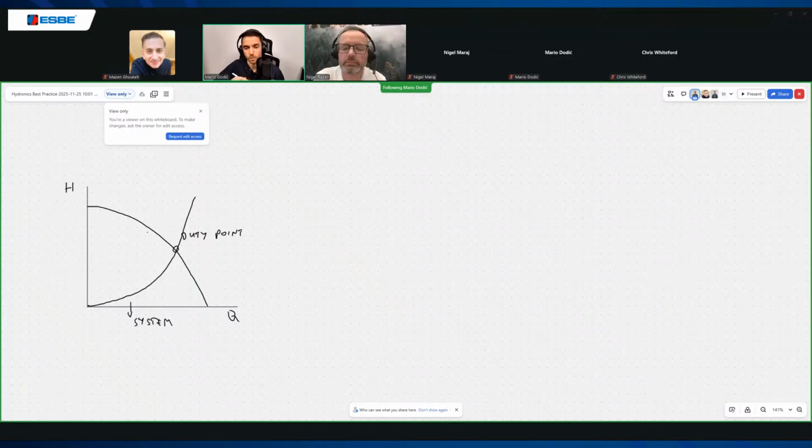Because when we are pushing more flows, we are increasing the pressure. And at some point, let's say, here is 40 liters per minute. This is the duty point of the pump. So intersection between pump curve and, let's say, here is 40 kilopascal. So this is important. So how we are choosing components, what we will see soon, will affect how our pump is working.